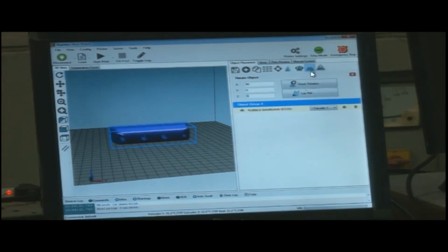So next is view cross section. This icon is view cross section. Sometimes we need to see what is in the inside portion of this job. For example, we have got this CAD model from the customer. The customer has just made this model and brought it for us, so we are not aware of what the profile inside is. Are there any holes, some pockets, some countersink holes?